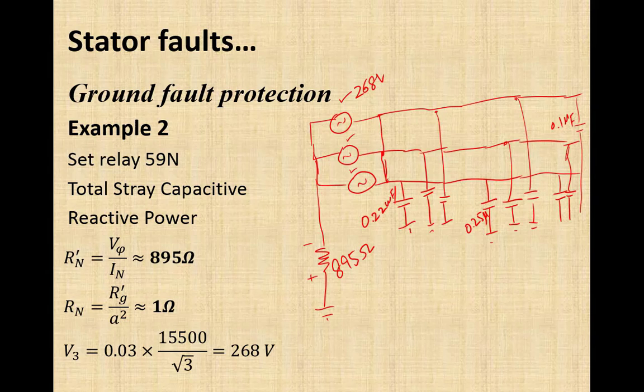So next, when I have combined these three terminals together, what has happened to these stray capacitances? All the three stray capacitances in all three phases have become parallel, and the stray capacitance of generator winding, stray capacitance of lightning arrestor, and stray capacitance of the transformer will be in parallel with each other as well. So we know that parallel capacitances get added directly. So what will be the total stray capacitance after combining all of them together?